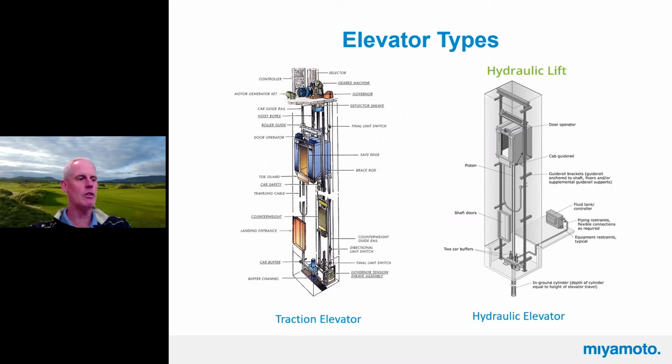I was going to try to get some good pictures or drawings of Veronica's team, and we did a recent wood building, just a 2-story building. Certainly they do elevators in wood buildings, but I think this one was just kind of quirky. So we wound up putting 4 steel columns in each of the corners, and we put an HSS, I don't know, was it a 10x5 beam or something, at each floor level? We attached the guide rails to that. It just made it a lot cleaner.